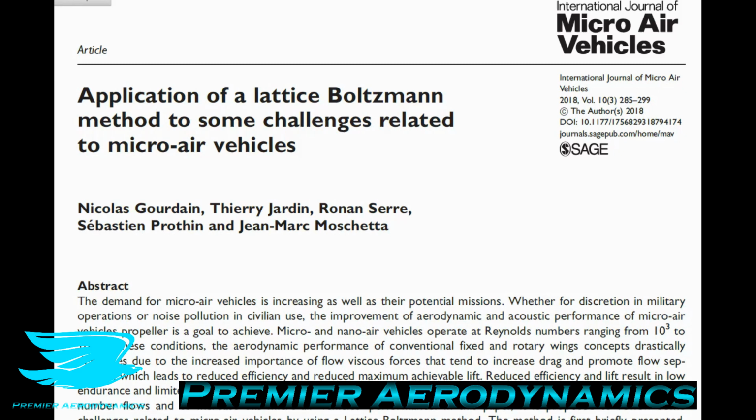So that's the general idea of the Lattice Boltzmann method. Oh, sorry, I should also mention what properties they're calculating. Where the Navier-Stokes equations are calculating the macroscopic properties such as density, pressure, and even velocity, the Lattice Boltzmann method is calculating the actual microscopic properties, such as just the velocity. And then from there, you can calculate what the pressure and the densities are from knowing these microscopic properties. That's how this works. They're using different equations. So that's a general crash course in how the Lattice Boltzmann method differs to the Navier-Stokes method.